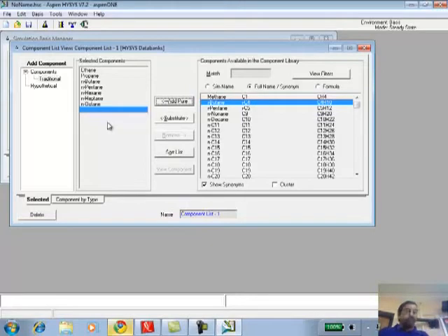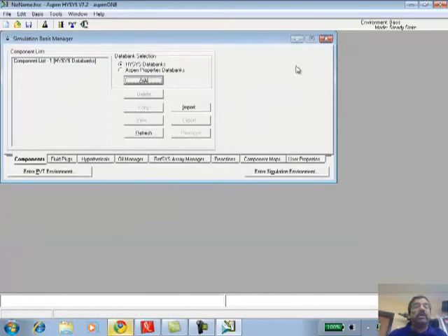But as I said, the database is huge, and you can search by the name, search by the formula, you can put filters, you can match, things like that, if you're looking for a particular component in your system that you want to simulate. So here I'm just taking a pure hydrocarbon system, and once you have selected, you close the window, and the next thing that you have to do is fluid packages.